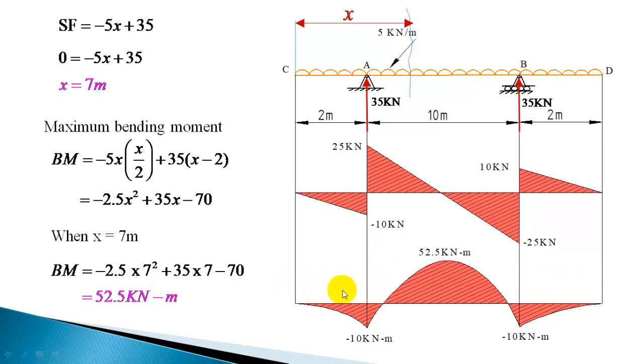Okay. So we will always write the equation from left end. So we can find out the distance from left end, this distance, and again this distance to this point from left end. What is the distance? So that is point of contraflexure. So you can locate the point of contraflexure. So first thing is you have to identify which section these points are coming. This point of contraflexure is coming in the section AB. It is coming in the section AB itself. Both the points are in the section AB.